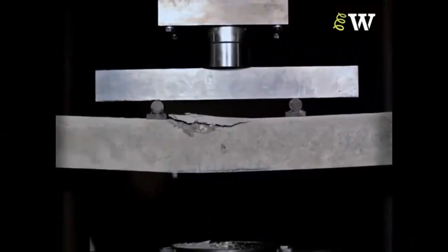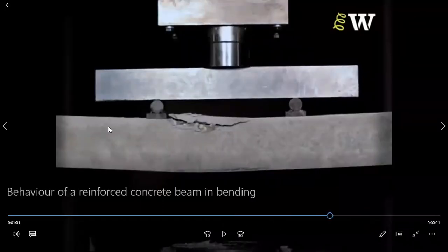See, whenever you find cracks like this, you can see the vertical crack and the main reinforcement failing here. So this is how the beam fails in bending, like a pure bending. See, there is no failure at supports. You can clearly observe at the left end and right end, you can't find any kind of cracks.